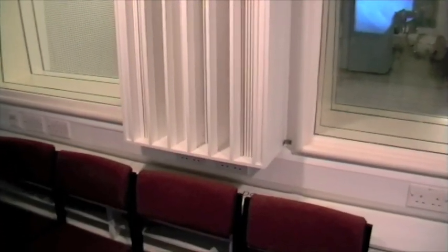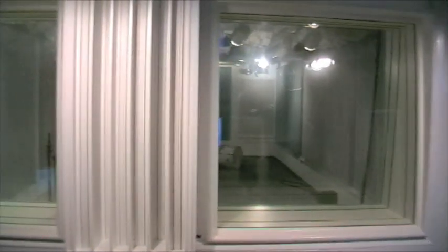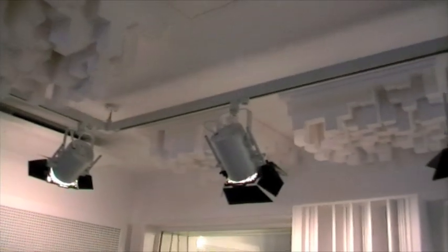On the contrary, the back of the studio features custom diffusers which aim to evenly spread the arriving sound waves. As you can notice, the acoustic panels on the ceiling, along with the thick double windows, are angled, limiting room modes, while a broadband absorber is situated in the back of the left side wall. 3D diffusers are situated at the back side of the ceiling for further diffusion.